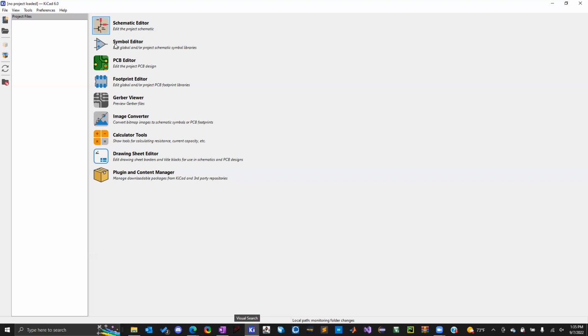The way you order the pins in the symbol doesn't matter because KiCad will handle everything for the footprint you associate to it and put each pin where it should be for the actual component. So the symbol usually looks nothing like what the actual board would look like. It's just to visually see all the connections. Then when you go to the PCB editor here and start laying out all your components, that's when KiCad will say, here are all the footprints you assigned to your components, this is what they look like. And now it's up to you to arrange it how you want and then make all the traces and everything.